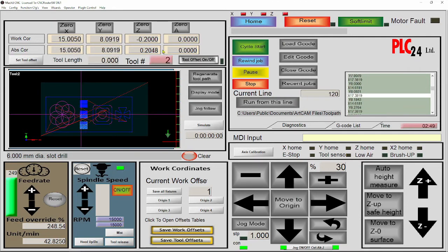And this is the absolute coordinate and work coordinate here. The absolute coordinate is related to the machine home position or the machine sensors. And the work coordinate, we can zero it whenever we want and wherever we want before running the program. I made a zero here at this point, which is compatible with our drawing. So it's almost done with the pocketing.